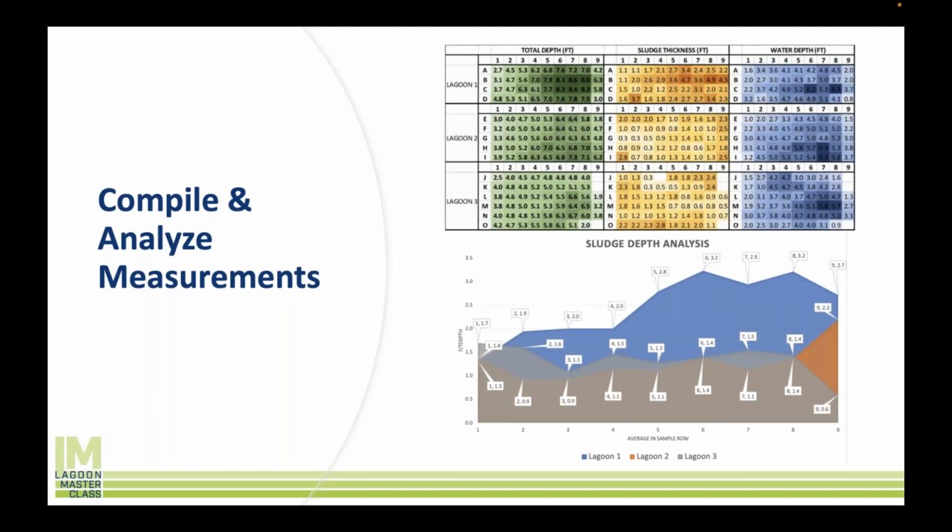Lagoon 2 seems to have a little less sludge than Lagoon 3 does, which is sort of surprising in a way. But when you consider that this lagoon system was actually aerated, it kind of makes sense, because you keep some solids suspended, you break down solids in Lagoon 2, and then whatever is flowing into Lagoon 3 is a quiescent lagoon, and those solids tend to settle, and they settle down in that final polishing lagoon, which essentially acts as a clarifier for the whole system.